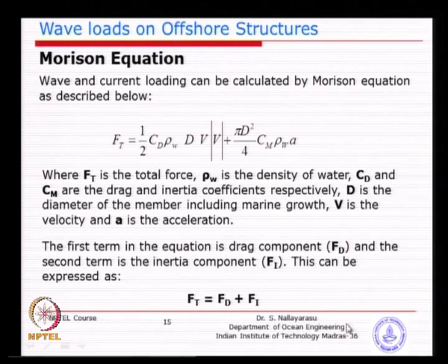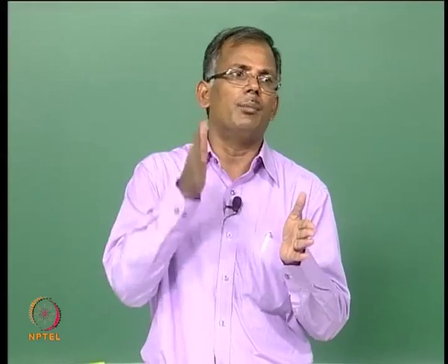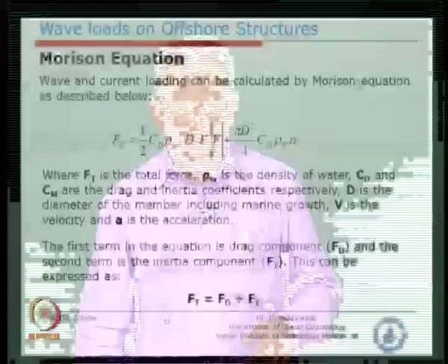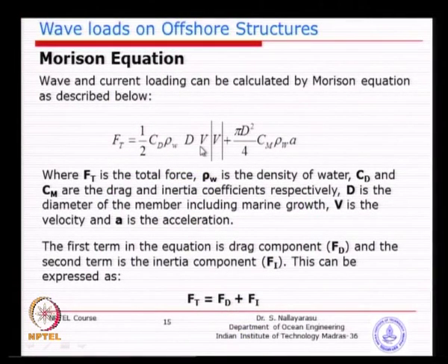and basically we need to find out at what time this will be maximum, because you take one wave cycle, a wave period of 10 seconds, and you monitor the force every 0.5 second or 1 second. So, you just calculate, for example, every 1 second, 10 times you do the computation. So, from 0 second to 10 seconds you have 10 computations, 10 different values will be arrived at for the total force. Now, whichever is higher, that will be the design force, which I am sure you will all agree, because we want to design for the maximum forces, so that the response is maximized and the structure is safe.